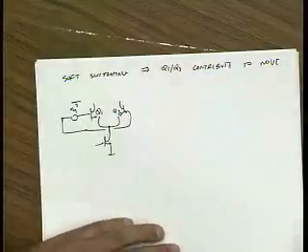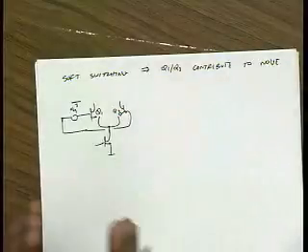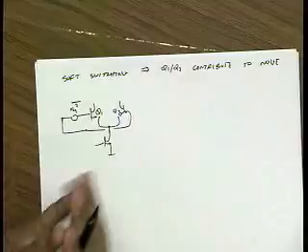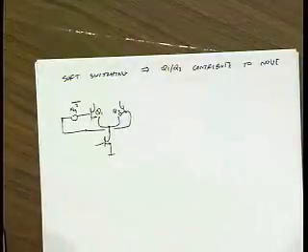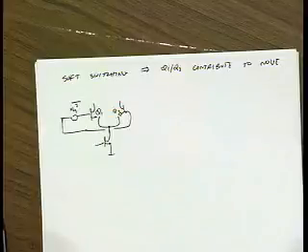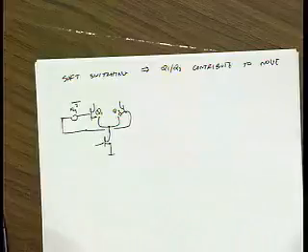So that's why we like to have a very large LO swing so that we minimize what we call the on time of both transistors. Okay? Question? So in general, when you have two input ports like this, how do you characterize noise figure? You have two different noise figures for different inputs?